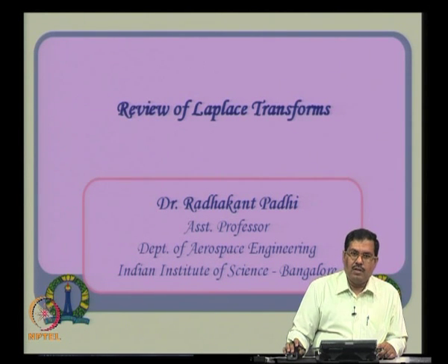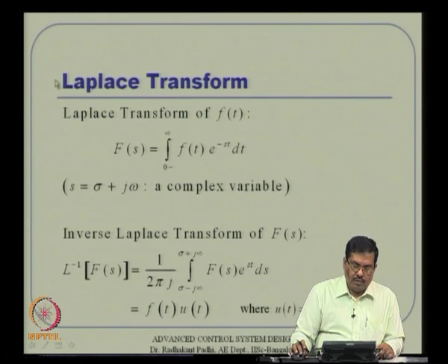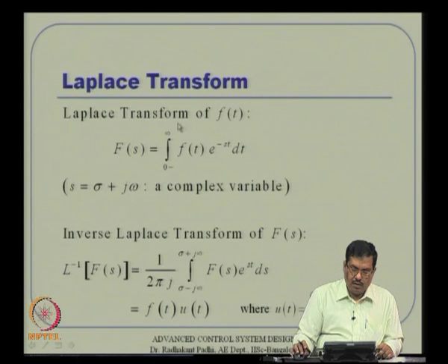First thing, before we talk about any classical control system, is a review of Laplace transforms. So, let us see what that transform does. The Laplace transform of any function f of t can be defined as an integral from 0 to infinity, strictly speaking 0 minus, so just a little bit before 0, of f of t e to the power minus s t dt, where s in general is a complex variable, with sigma the real part and omega the imaginary part of it.